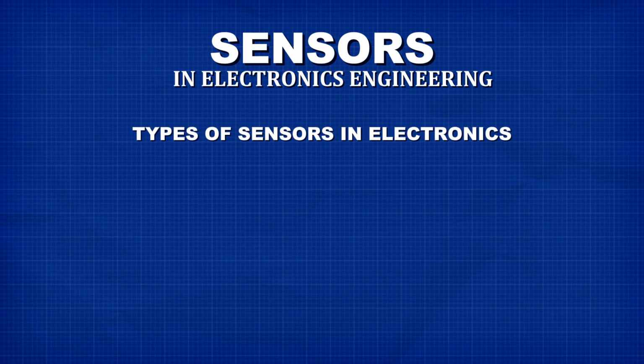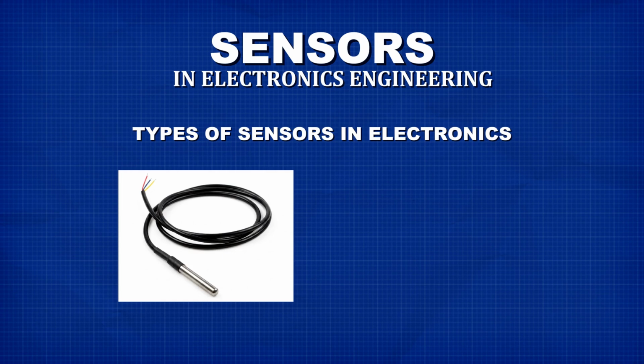So now let's look at some common types of sensors used in electronics. 1. Temperature sensor. A temperature sensor detects heat or temperature changes. It can be used in thermostats, battery monitoring, cooling systems, incubators, weather stations, and industrial machines. Examples include LM35, Thermistor, DHT11, DHT22, and DS18B20. Some temperature sensors give analog output. Some give digital output.